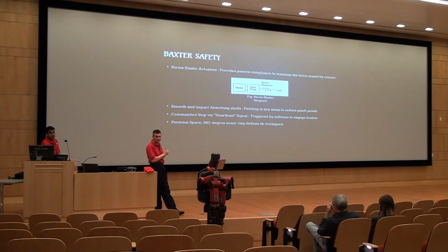Yes? So I've worked with industrial robots, and we've had to cage them, like you said in your initial presentation, with light curtains or even safety mats around that would shut all the actuator powers down if somebody approached the work site. And I heard the presentation at IEEE that was given on the Baxter robot earlier this year. I was still wondering, do you consider this safety software interlocked or hardware interlocked? Because at the time, the safety people wouldn't let us do anything where software was in charge of the safety of the robot not harming or killing somebody.